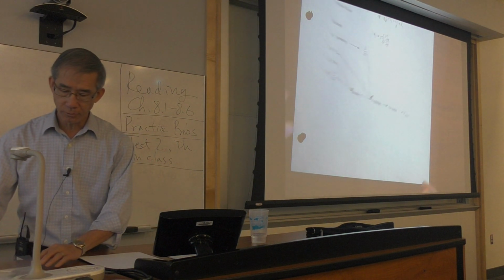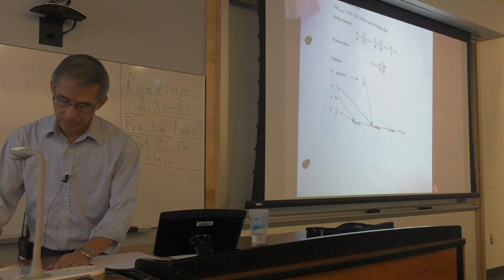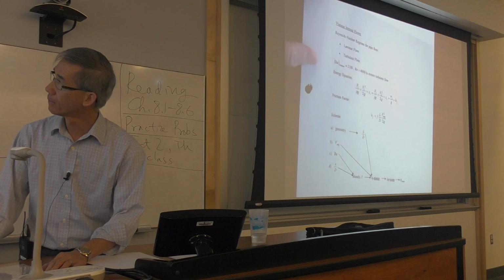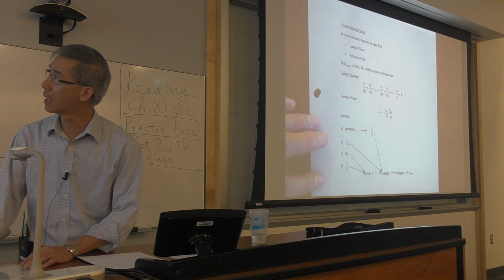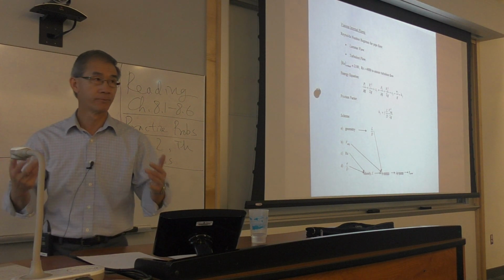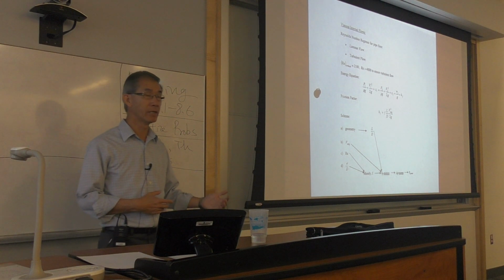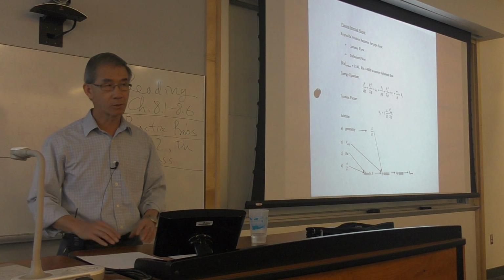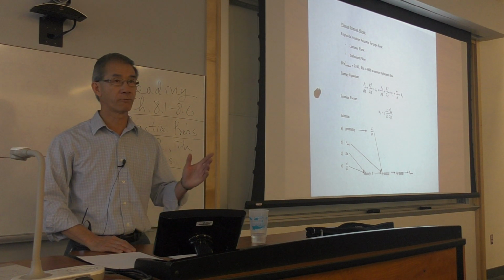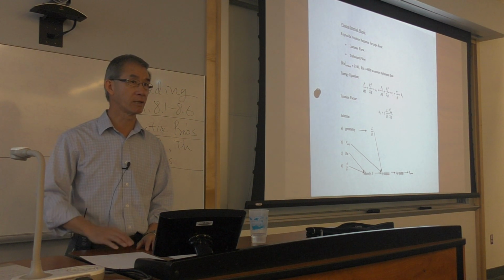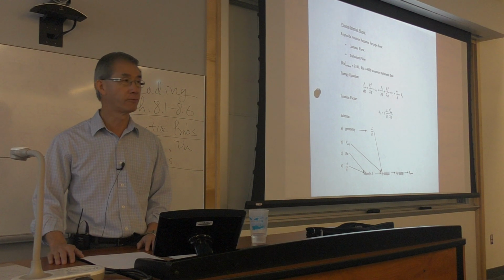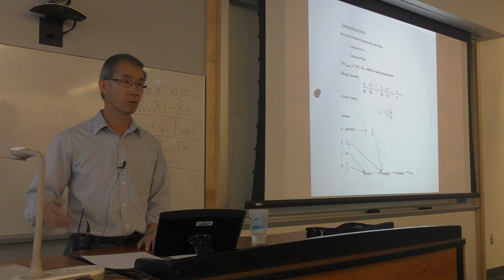And from there, we move on to chapter 8, which is the pipe flow. And within that, we talk about laminar versus turbulent flow, chaos versus layers, and transitional Reynolds number. Laminar flow is a very, very small percentage of real-life application, 2% of engineering problems. The majority of pipe flow, at least, is in the turbulent regime.